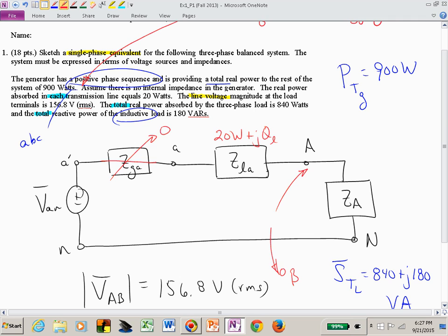And one of the nice things about this is then you could start computing capital I sub A. If you have all the impedances and you have the generator voltage, now it's, I think, trivial to compute the line current if you needed it. Or can we get that from some of this other information? Do you see how you would start attacking this problem?